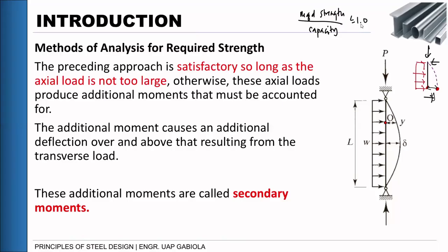Okay, and then we also have an axial force, and of course, since this axial force produces a moment papunta dun sa original na position ng ating beam, so that moment is actually the secondary moment that we need to account for. Okay, so yung sa secondary moment, so kung this is P, this is also P, and then let's say yung deflection natin is y, so this moment is actually equals to P times y.